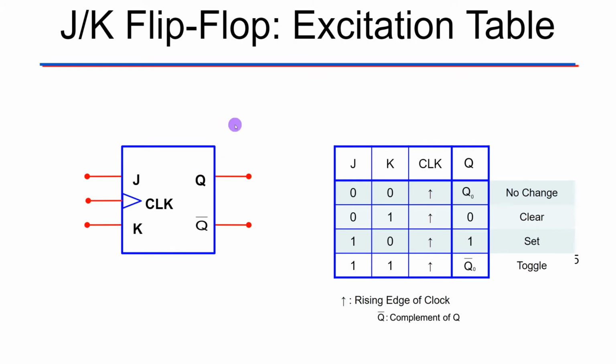And then we also have the other main variation of flip-flop that we work with in this class, which is the JK flip-flop. This is a very similar idea where we have a component that saves a single bit of information based on the inputs. The main difference between D and JK flip-flop, as you notice here, is we have a couple more options. Because we have not one but two control or input signals, that means we can think about having 4 total different possibilities in how we deal with this information.